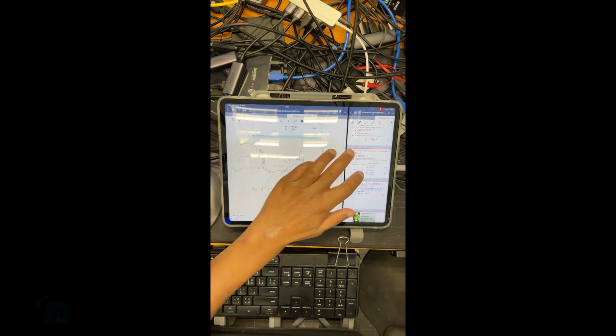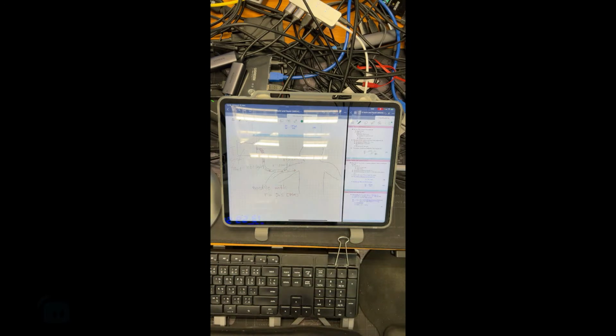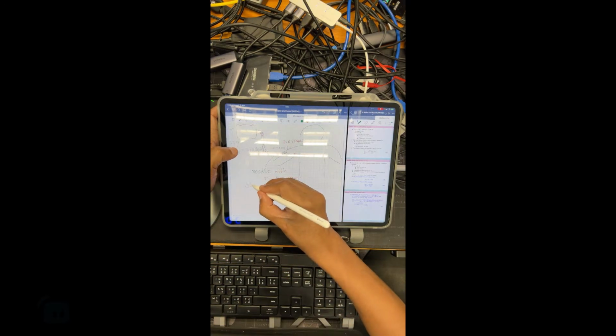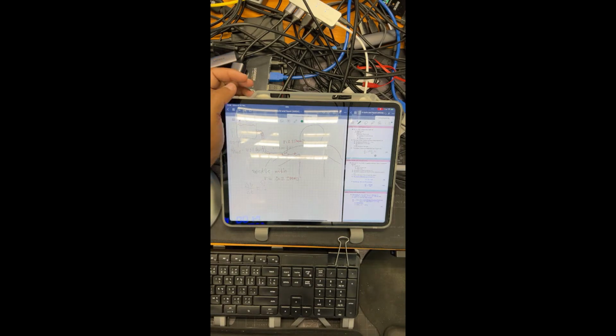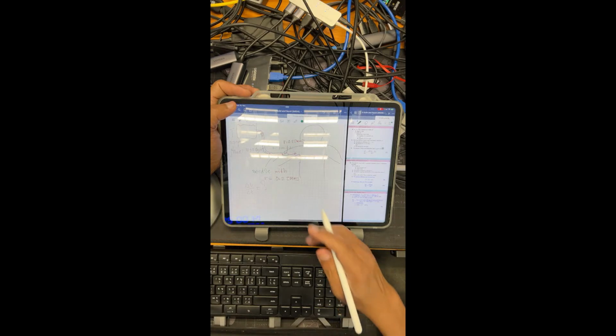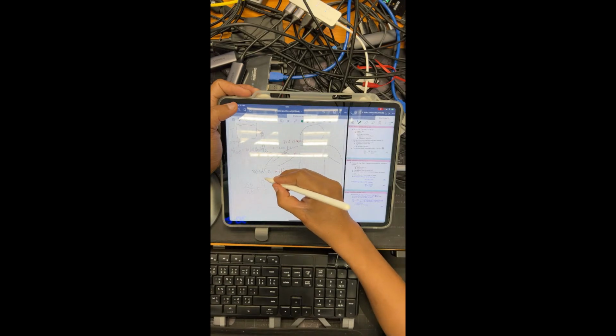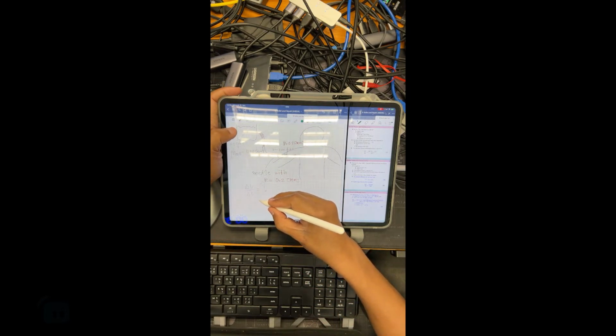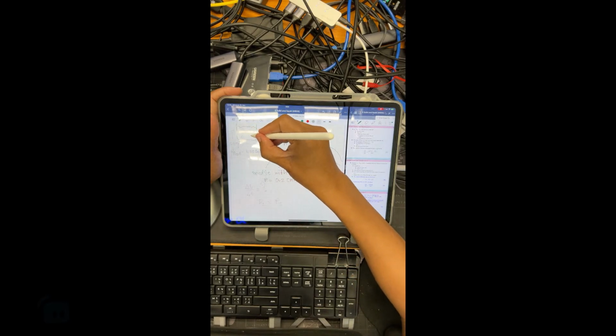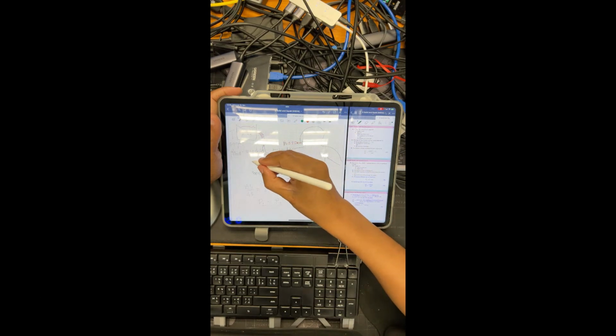So now we are going to use this formula, the Poiseuille formula. What they want to know is the rate of flow through the needle. So the question is delta V by delta T. What is that? We're going to use the Poiseuille formula, and we need to know R, the capital one, the not small one. R is already there, and the pressure difference, P1 minus P2. P1 is right here, and here is P2, the pressure at this level.